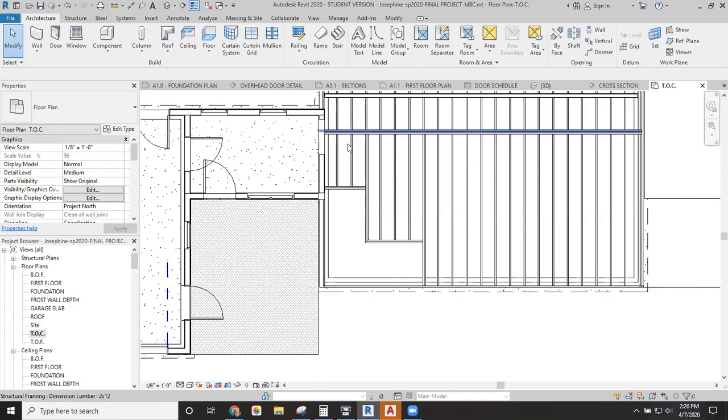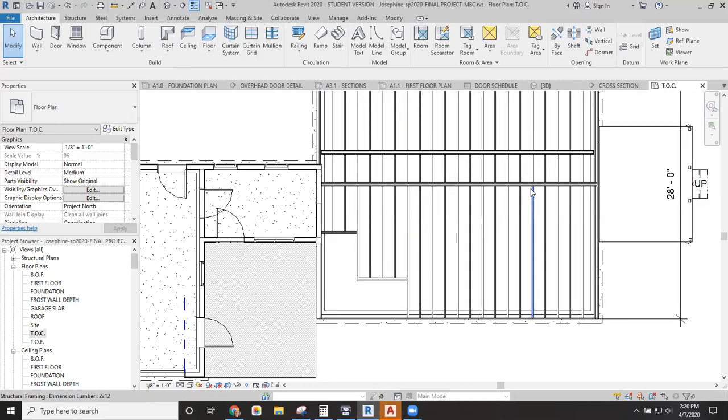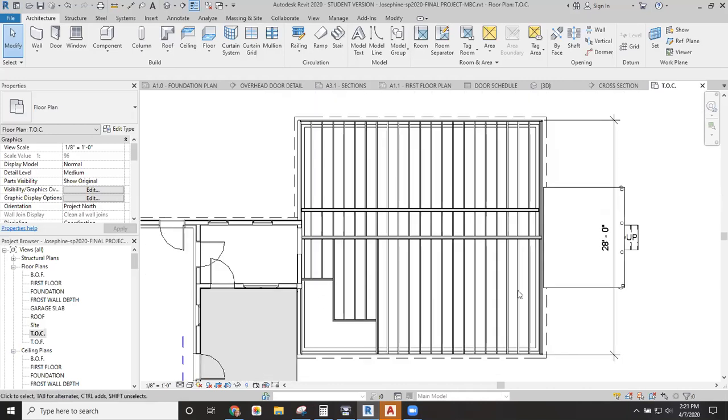If I wanted to design this as a straight set of stairs, I could probably fit it in here, but then I wouldn't be able to get the door in here, based off of where the mudroom is relative to the house position. So this is a perfectly fine way to do it. I still kept my beam in the center and just moved the head of my stairs where I needed it to be to create that L-shaped opening in the corner.